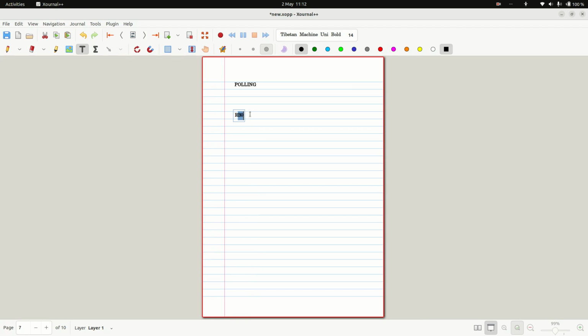So I am configuring this as the source of external input. Here I am going to use two LEDs, LED1 and LED2. LED1 is for interrupt identification, LED2 is for the digital keypad interface. If I am constantly reading, that is considered polling.